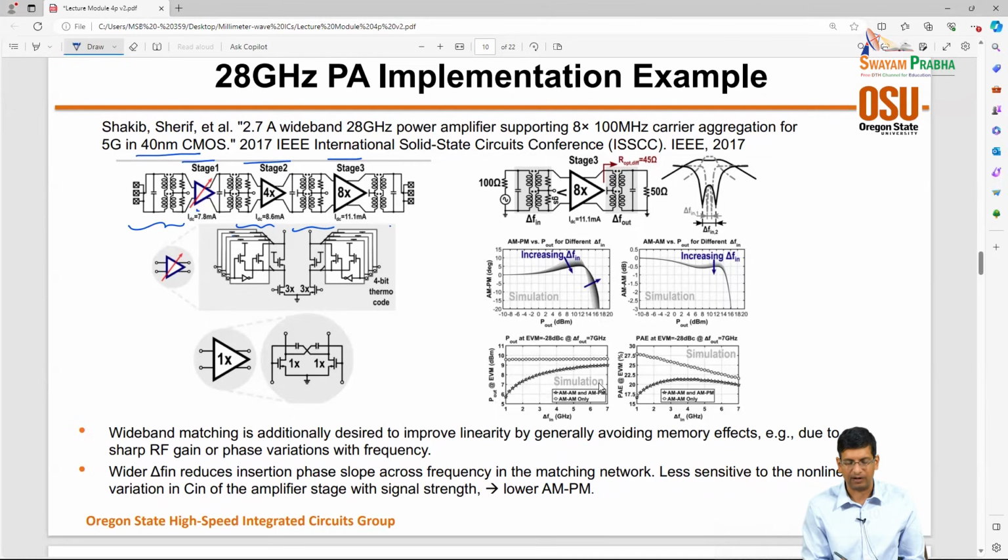You basically have some unit cell devices here, but the driver is 4x and the PA is 8x of the unit cells, right? So this is typically a very conventional way of scaling, where your driver is about half the PA, right? So you're counting on being able to have sufficient gain. If you have about 10 dB gain in the PA, this sort of split works very reasonably, right? And if you're operating with about 10 dB gain in the PA, your Fmax should be about 3x your operating frequency, right? So these numbers just all sort of tie together as you pick your technology.